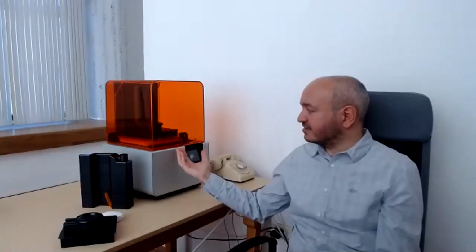After you clean it, the second step is post-curing. Since the laser itself is not enough for curing the material completely, we put it into a curing oven, a very simple one. Again, if you have time, I may show it to you at the end of the lecture. Once you do the post-curing, which takes about 30 minutes, usually at around 60 degrees, you will be done with the fabrication. Your part will be ready to use. Its strength will be good enough, and you can use it in your desired application.